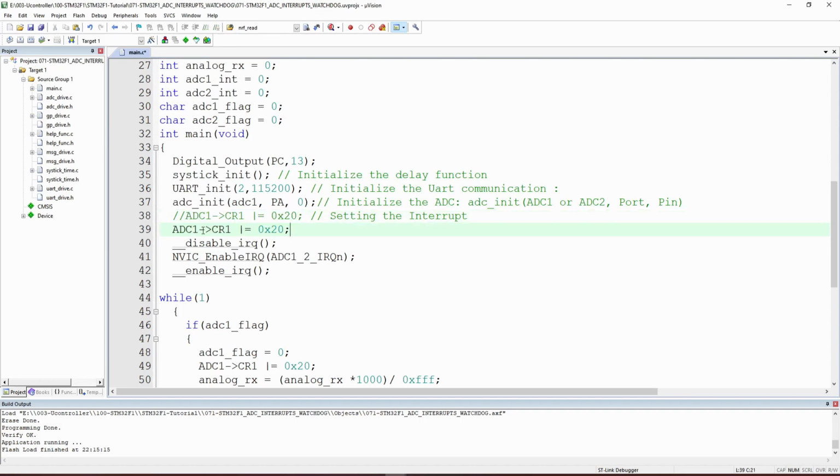Here, instead of putting ADC for this one 02, let's copy the same, and for this one we put 80 hexadecimal because it's the first one, and we add 1 2 3 4 5 zeros. This is how we enable the watchdog.